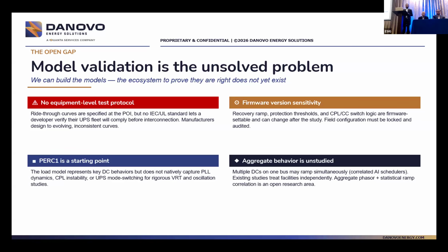And so what you are really trying to plan and design for, you need to have conversations to understand where that whole industry is moving. We are hearing a lot about, for example, at the server hardware level, how much you size the cap banks for. That helps a lot with being able to mitigate or manage a lot of the high frequency oscillations, manage a lot of the ride-through events. So you might not really need another solution, but we need to see where the technology evolves to, right?